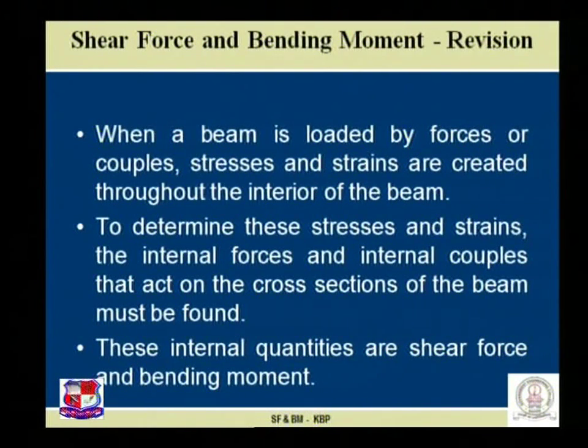When a beam is loaded by forces or couples, stresses and strains are created throughout the interior of the beam. These internal quantities are referred to as shear force and bending moment. Our intention in today's study is to find this internal quantity along the length of the beam, and then plot that variation along the length of the beam, which is termed the shear force and bending moment diagrams.